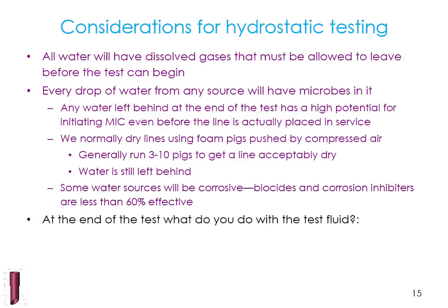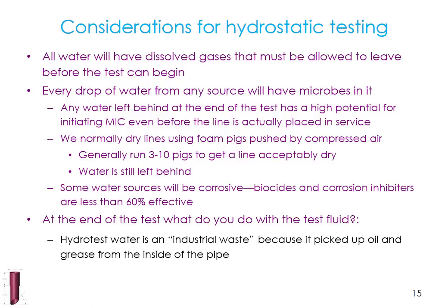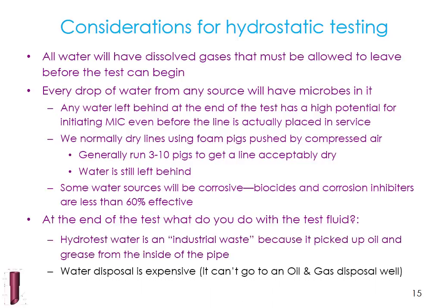At the end of the test, what do you do with the test fluid? Well, hydrotest water is an industrial waste because it picked up oil and grease and corrosion products from inside the pipe. So your water disposal is expensive. It's now an industrial waste, not an oil and gas waste. So I can't go to an oil and gas disposal well with it. I have to take it to an industrial water disposal.